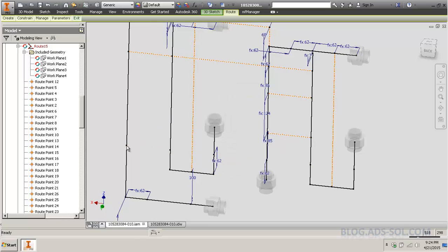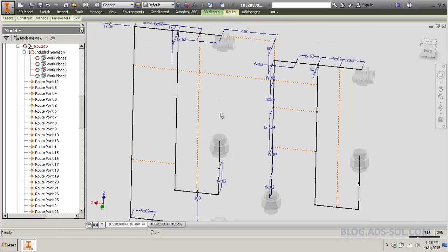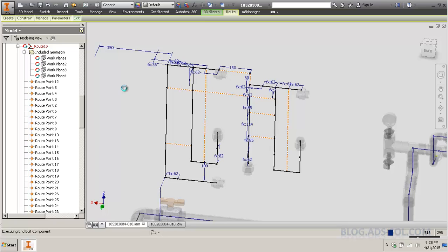You can remove this and then draw a construction line up to here, parallel with that one, coincide here, and then you can just say this point will be on this line, this point along this line, and this point along that line. Same for the last one, and you can control it all. Just say plus 20. You can control it all with one dimension. Once you start using it, you'll get used to it, and you might find it useful. Right, so let's finish this.